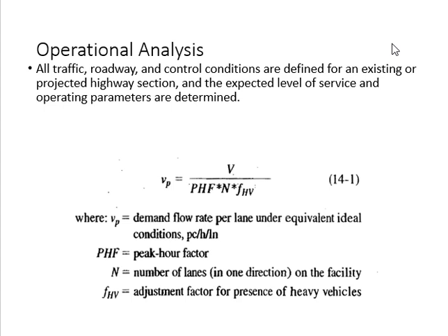Forget that here. Peak hour factor converts flow rate to volume and volume to flow rate. The 4 is for flow to flow rate. Here I am saying flow rate to volume. So volume to flow rate and back, peak hour factor. Flow to flow rate and back, 4. Clear everybody? Okay. So this is why volume became flow rate.